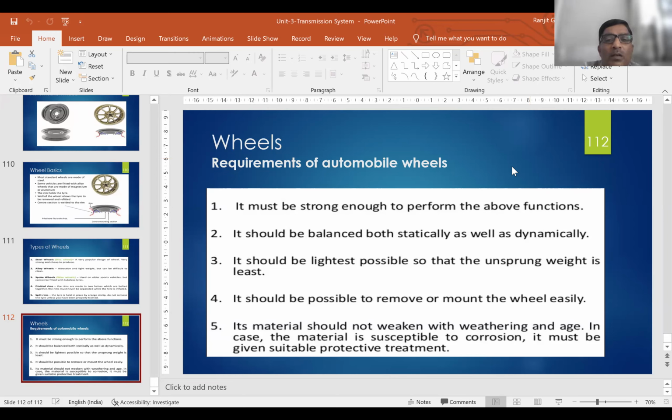So this is one of the photographs of an actual steering system. This one is the tie rod. This is the knuckle arm. So this needs to pull in this direction with the help of this tie rod, and the knuckle or steering spindle is given on the right side, which is not shown here. So this is the wheel hub. This has to steer. Automatically the wheel is going to steer.